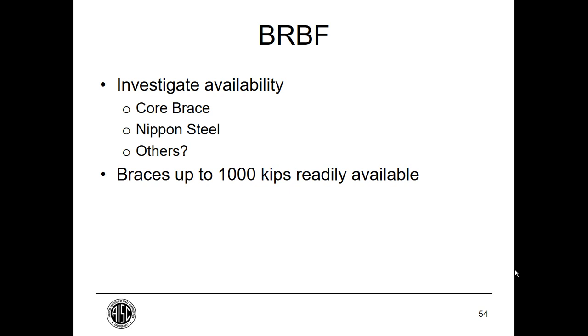When you get above 1,000 kips, the braces become more special, and you should definitely verify that they are available and that testing covers the brace that you want to specify, because it is a tested system.